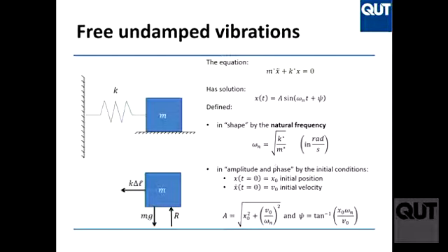Okay, the formulas for amplitude and phase are here. Obviously, intuitively, amplitude depends on x0, which is the position at time 0, and the velocity at time 0, the speed at time 0. Okay? What does it mean? If at time equal to 0, I have just a tiny displacement from here and 0 velocity, that's not going to vibrate much. Agreed? If I have a massive displacement at the beginning and I drop it, that's going to vibrate much more.